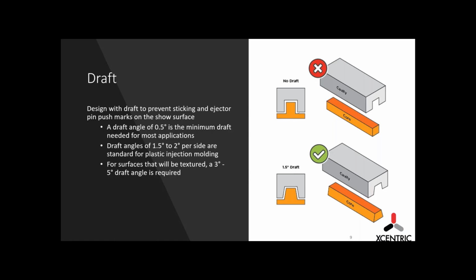Most of your production type parts, high volume parts, million pieces plus, are used with hot runner systems, which we can do, but we don't do a ton of them because that's more for high volume. Most of the gates we do are edge gates, so they'll be visible along the parting line or the outside of the part. You can do sub gates for cosmetic type parts, and there's a couple other gate types, but you should be thinking about it. You don't necessarily have to design it in, but be thinking about it when designing.